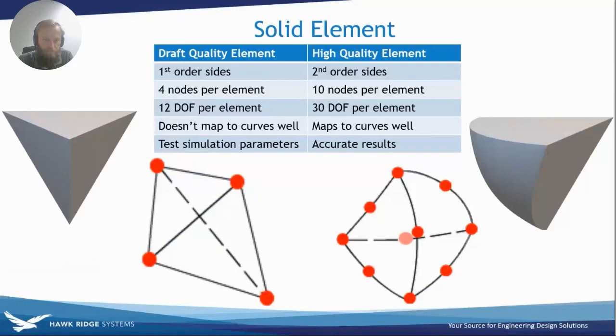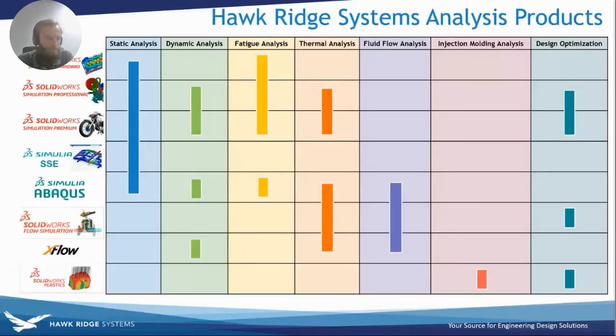Any tips for going between beam elements, solids, and sheet metal when it comes to meshes? So again, if you are designing using weldments or sheet metal surfaces or just using normal SolidWorks features, when you throw that into simulation, it'll automatically convert it to the appropriate mesh type. If you have all solid components and you want to convert to a shell, you can right click on that body in the sim tree and say use selected faces to convert to a shell or convert to a beam. So it's just a simple right click on those bodies to convert from one mesh type to the other. Or again, if you designed it in those formats, it'll do it automatically.